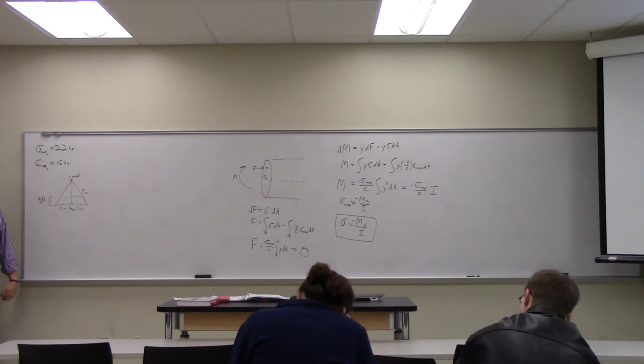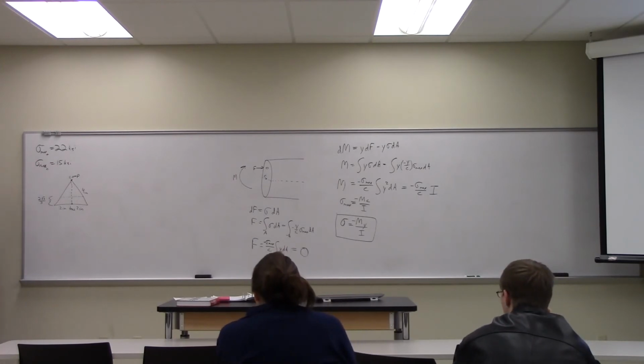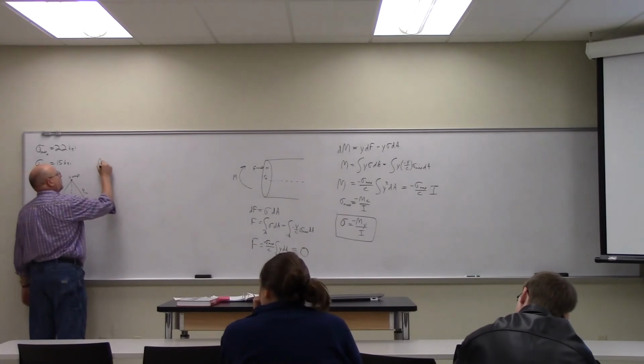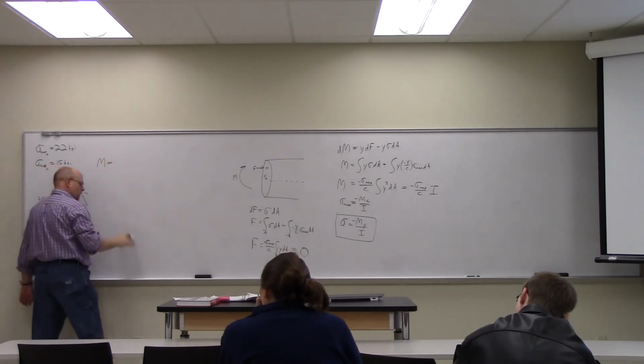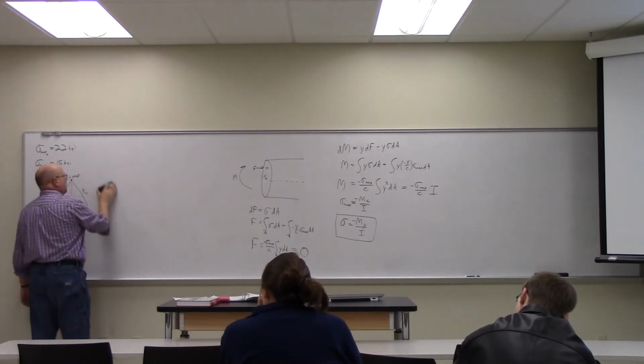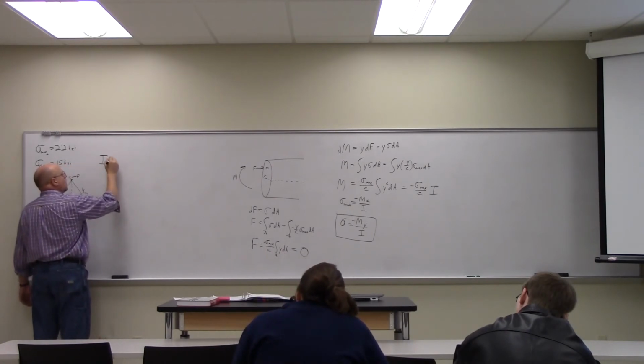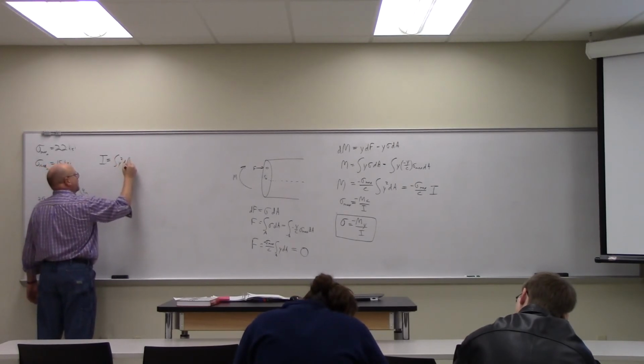So what do we do? Well, we know our sigma max, and we can solve for our moment of inertia. So we just set our equation. Moment of inertia equals what? Integral of y squared dA.